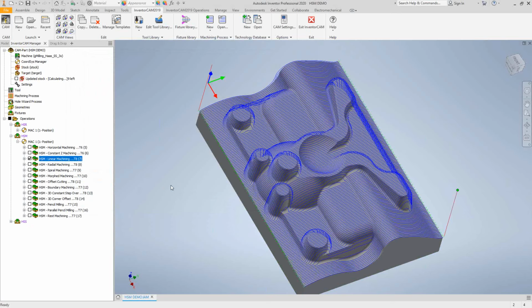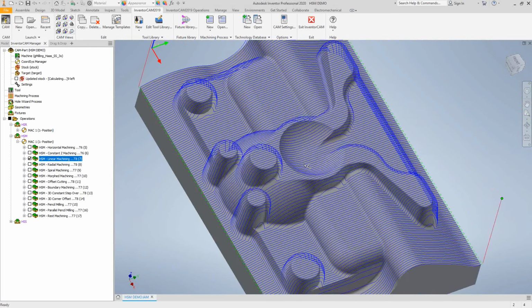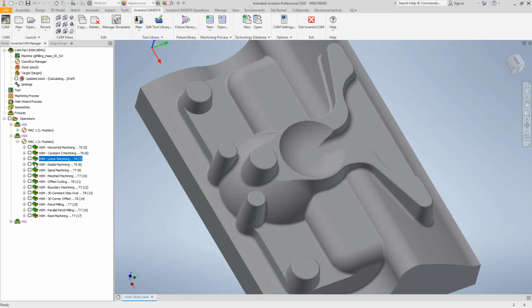If we look at the linear toolpath, certain areas look pretty nice. It might leave a good, clean finish. But if you look at some of these bosses, the tool riding along the side of a boss is not going to leave the best finish. There's a huge gap there, and it's not tailored to that in particular. This is why you want to use constraint boundaries. You might want to limit the travel of this tool to only the areas where it looks good, and stay away from these bosses. You can sketch a line, or use the edges from the solid to control the constraint boundaries further. But this is linear, you just tell it which direction you'd like it to go.